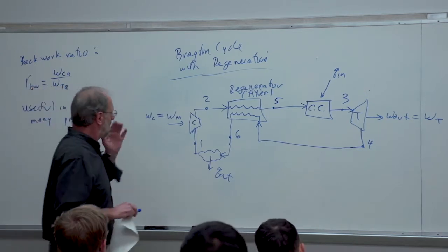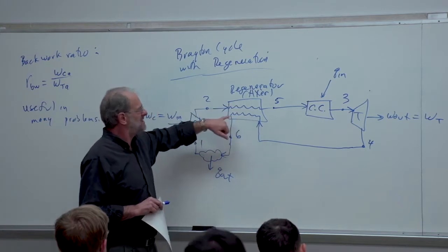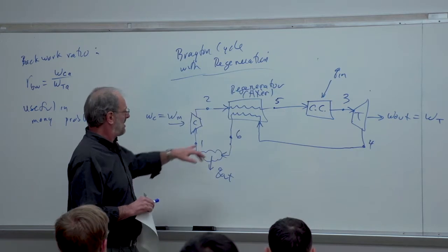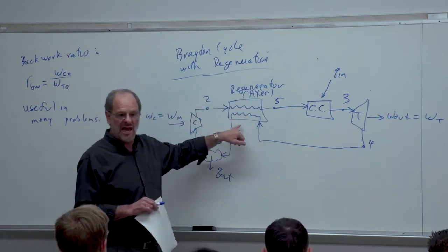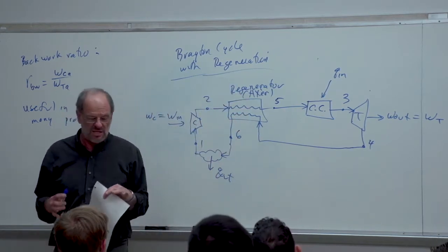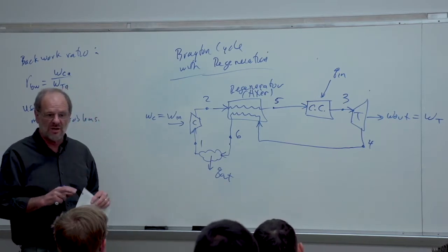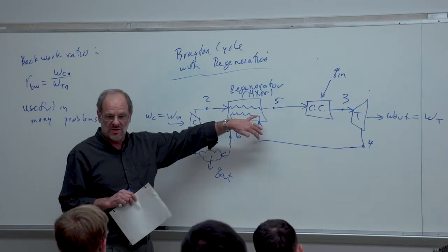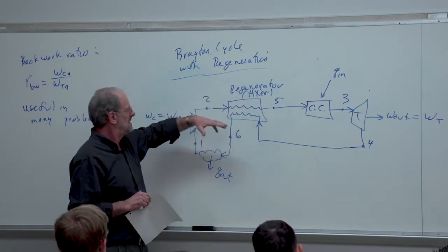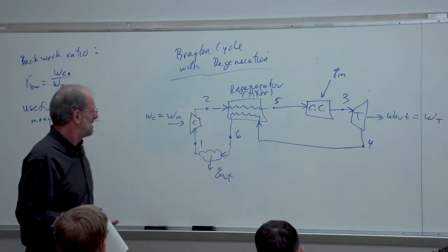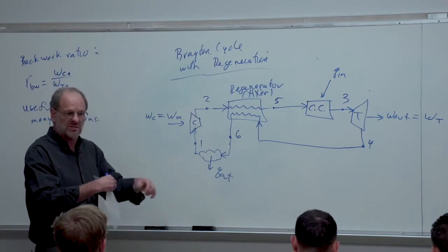Now, one thing I do want to note, yes, there is heat exchange within the regenerator. Obviously, it's called a heat exchanger, but we don't include any heat in or heat out. Keep in mind that these heat transfer terms, in fact, the work terms for that matter, have to cross the boundary of the system. The regenerator is entirely within the system, right? There's no heat coming in from an external source. There's no heat being rejected to an external sink. We simply have an internal exchange of heat.